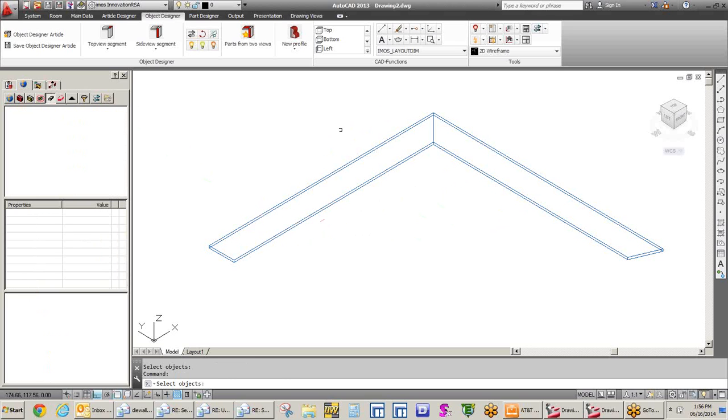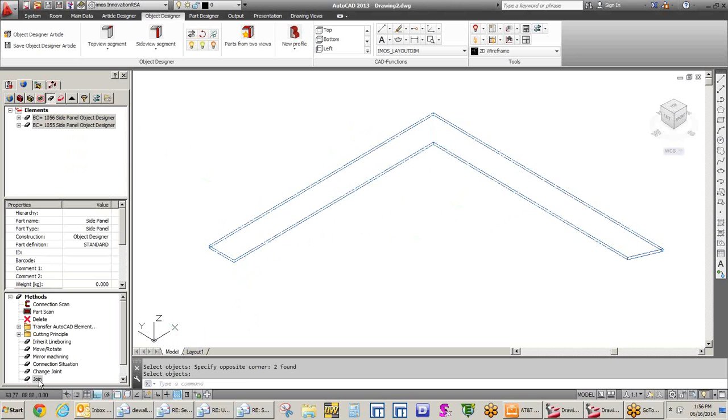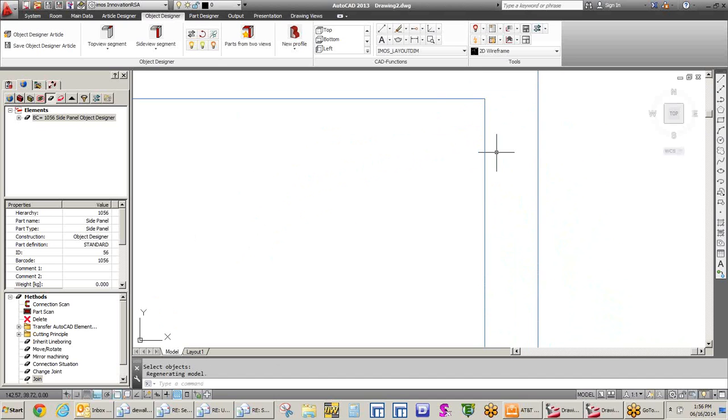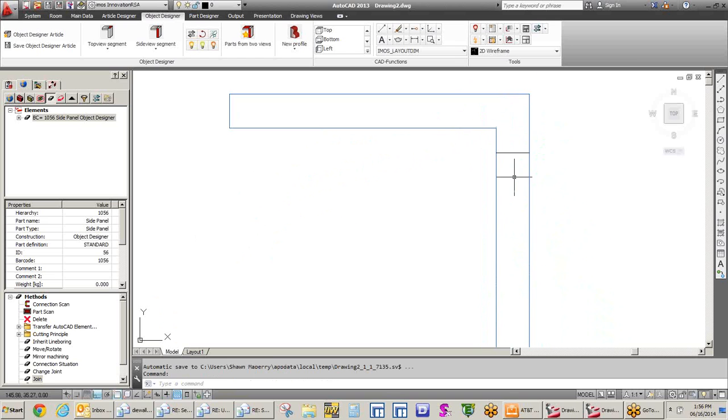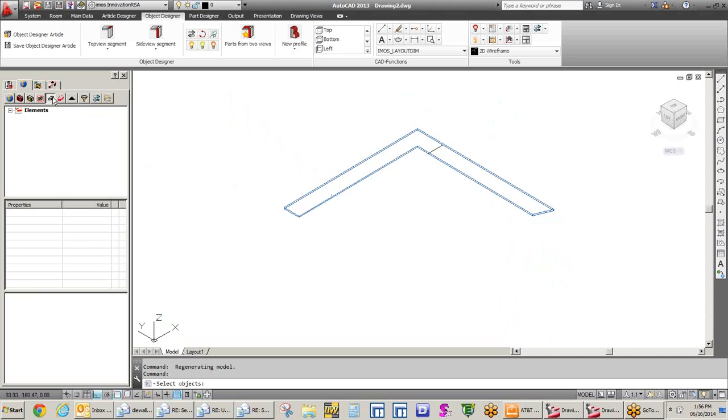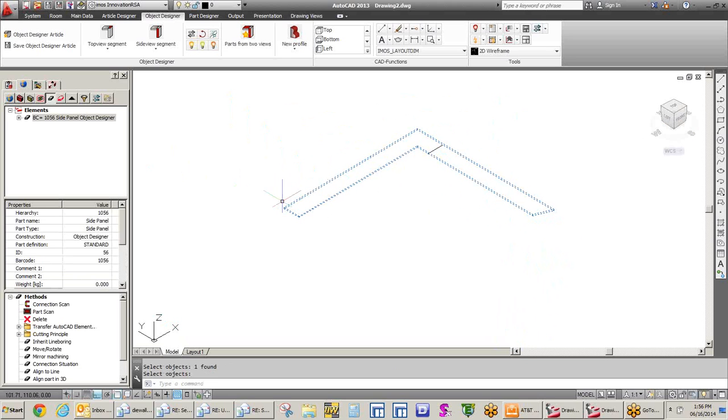What I'm going to do is select a couple of parts, right click on this, and click the button for join, and so now this became just one part. I'll flip up in a top view, and in this particular case I'm going to use a command such as polyline, literally just to draw a straight line or any kind of shaped line that you might want, where I've offset where I actually want this to be cut.